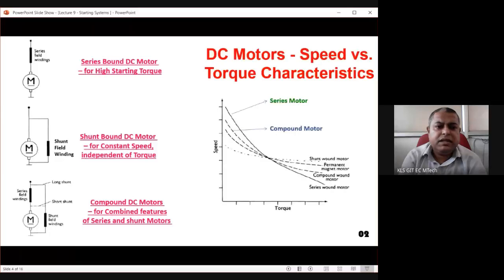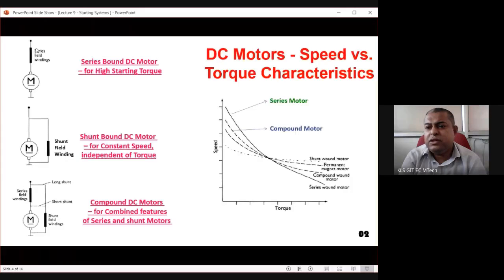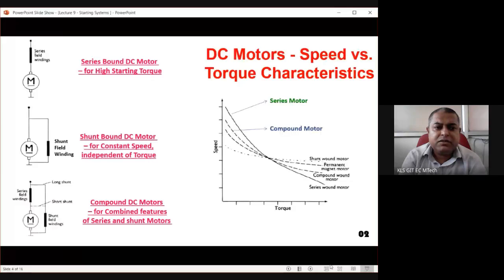The first one here is a starter motor. There is a winding in the armature. These motors follow Fleming's left hand rule. So there should be two inputs. The first input should be the input of electric current. Through this brush arrangement, it is connected to the armature. So this is the armature, there is an armature winding here, and there is a field winding.